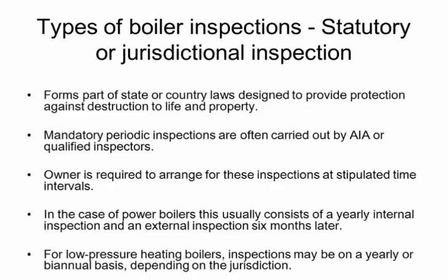The types of boiler inspections: stationary or jurisdictional inspections basically form part of a state or country laws designed to provide protection against destruction to life and property. As I mentioned, most countries' vessel designs are based on the American standard, including Australia, but there are differences with regards to standards and procedures from country to country.